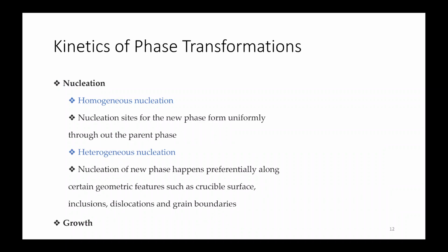Now we'll be going through some lecture notes. So first is the kinetics of phase transformation. So how your phase transformation, for example, from austenite to pearlite, or for example how the formation of nuclei from liquid to solid transformation takes place. These things exist. So first is nucleation. First there will be formation of some solid nuclei in liquid, or a nucleus in solid state of another phase. So firstly there will be nucleation, then there will be growth of that nucleus.